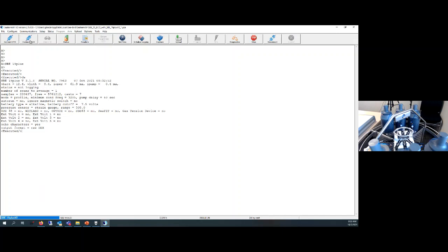Now, recall that I had shown those two cable diagrams and specified that you have to use a specific cable when working with your SBE 55. If you're not using the cable that has that pin 4 that's connecting to the DTR line, you won't be able to do this switching procedure. It will be stuck on either just the CTD or just the 55. In this case, I'm using the correct cable, so I'm able to switch back and forth between the two.